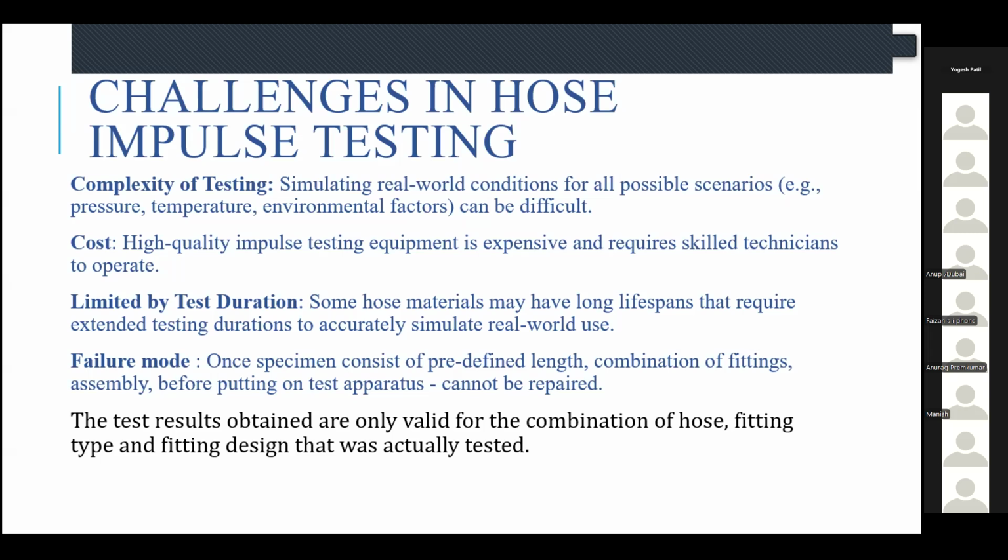Crucial when we declare the results. This is the combination of the hoses and fittings all together, so one bare hose cannot be tested together. Crimping and overall process development is very crucial. Many times the hose may be okay, and even the fitting may be okay, but the crimping criteria may not be. So the entire set of assemblies needs to go together.